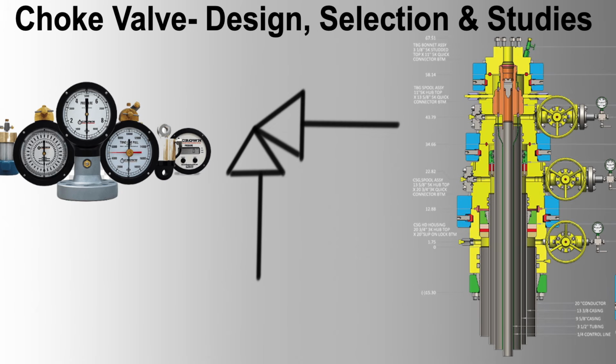2. Mounting. Secure mounting. Ensure the valve is securely mounted to withstand vibrations and pressure fluctuations. Proper alignment. Properly align the valve with the piping system to prevent stress and potential leaks. Operations. Monitoring. Real-time data. Continuously monitor upstream and downstream pressures using high-precision sensors. Implement alarms for abnormal pressure variations. Data analysis. Analyze pressure data to identify trends and potential issues before they escalate.